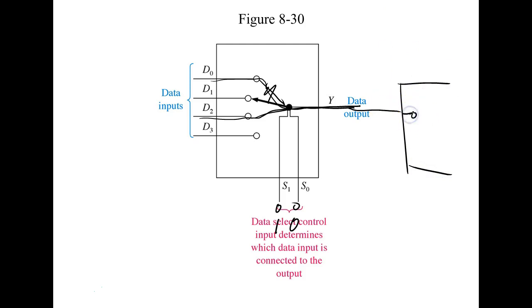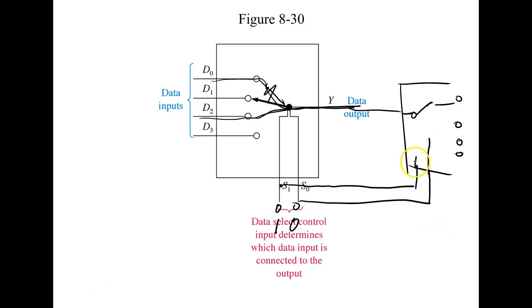The demultiplexer would be set up basically the same way. So let's say this is a 0. This would be 1, 2, 3. What we would do is we'd send the switch lines over here with it, and this would be controlling the position of the switch. So if I put zeros over here, this would select 0. This would come out and go back out 0, right? Understand? Now this is not very beneficial, but we're saving one wire.